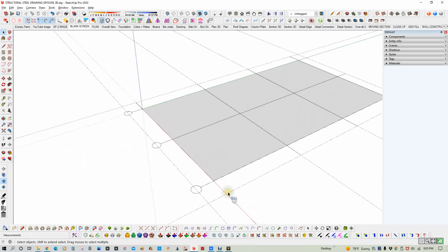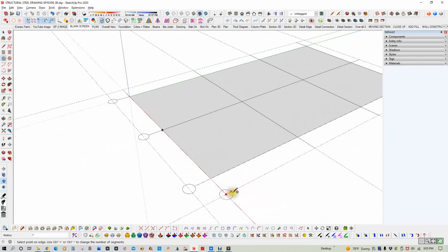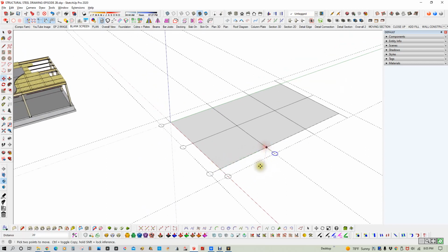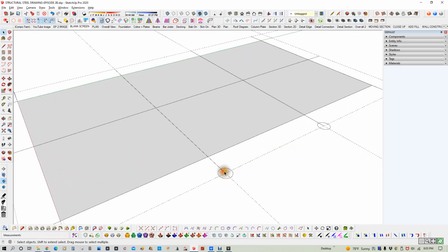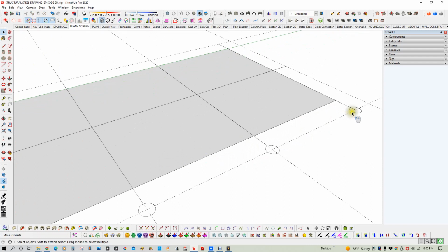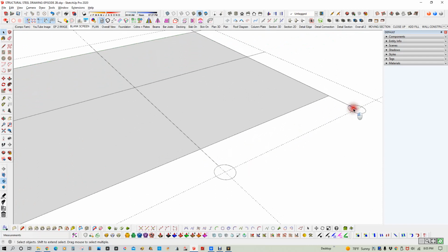And we'll do a circle again over here, 1 foot, erase the face, that extra line, and we'll do move, control again for a copy. Basically, when you do this, if I type in now 3x, I'm making an array. So similar to an AutoCAD array, this is the same thing. I think it actually works better, to tell you the truth. It's easier to deal with. You don't have to guess at spacings and things of that nature. They're all done on screen. It makes life a lot simpler.